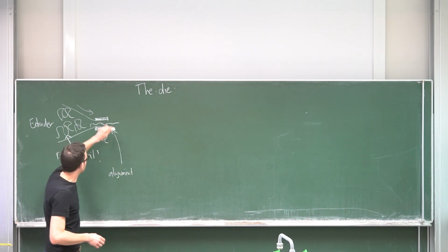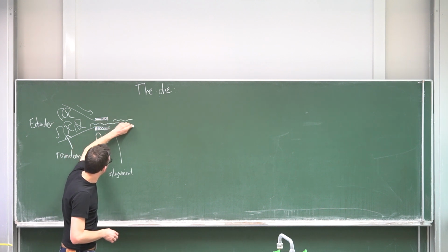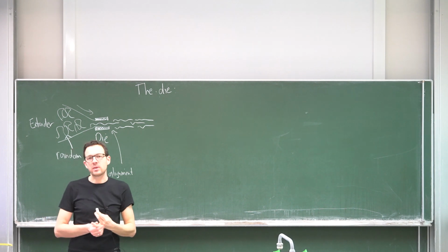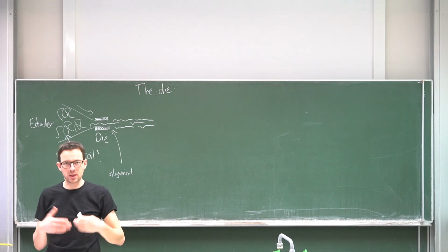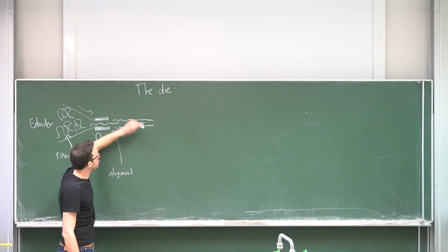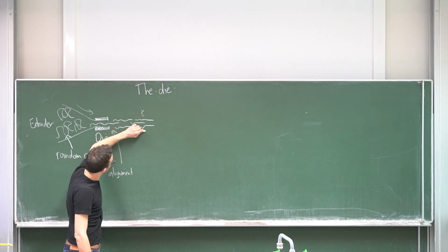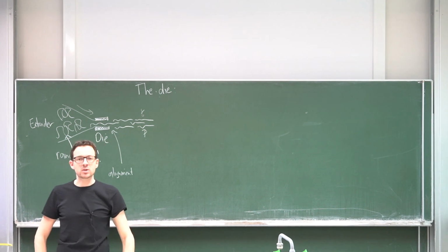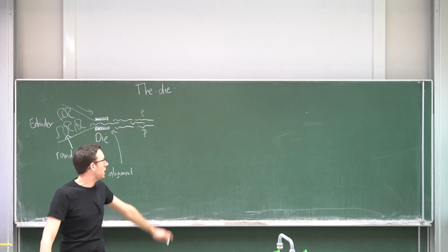So now they come out of the die, still aligned. And while they are still in a viscous state, or it takes some time for them to cool down, they experience that now there is no confining element anymore. And now the polymers realize, wait a minute, this is not really what I like to be in.